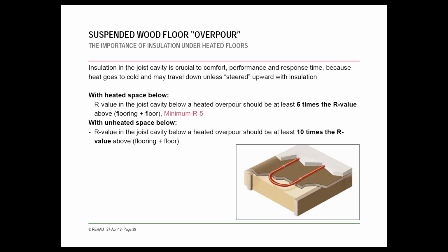Those ones have lower R values, but because they have an aluminum radiant area suspended between with an air gap from the air bubbles, it actually provides a higher insulation value than the R value would suggest.